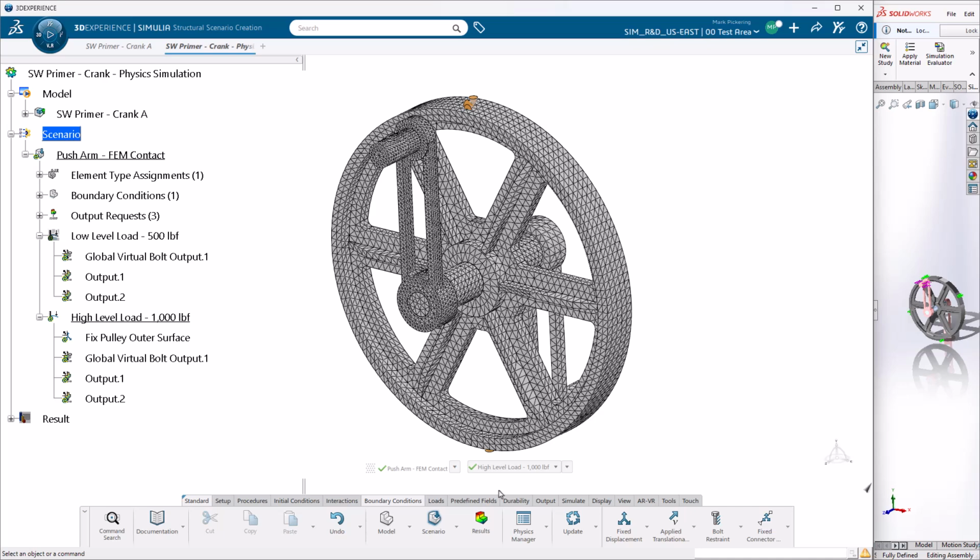In addition, there is a floating selector, which has drop-downs indicating the active analysis case and step. From these we can see that this boundary condition we just created is in the second step of the analysis. As such, this won't be present in the first step of the analysis.